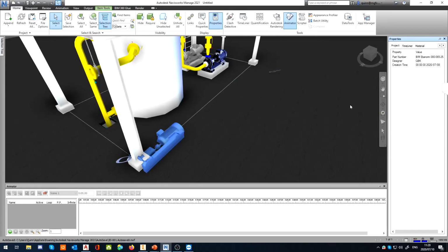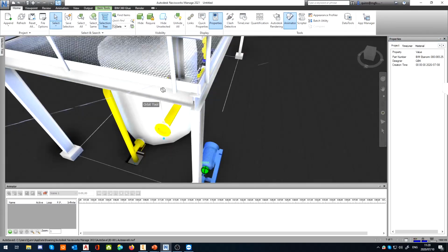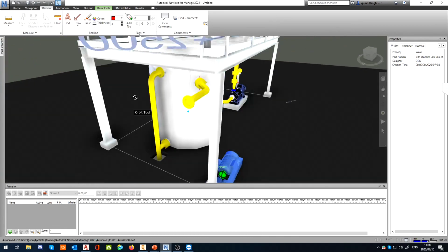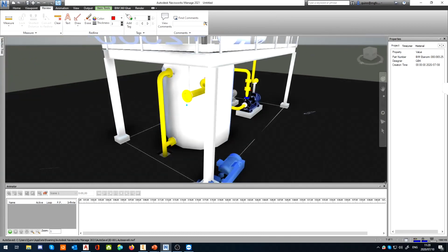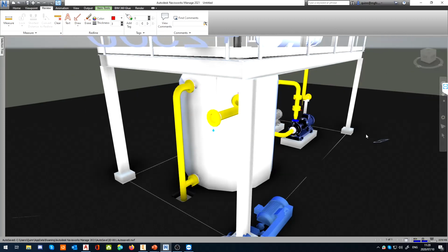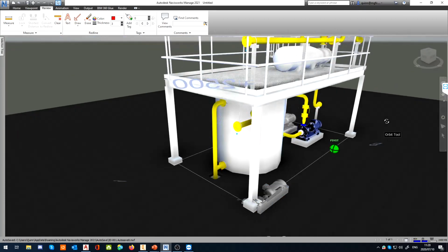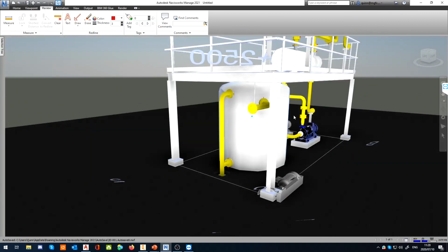By the way, this can also be done in Navisworks Freedom. They can do the markups, the viewpoint markups. So for review, they can do this in Navisworks Freedom, save it and send it back to you, so that you've also always got a copy of what was sent around. And then they've got the full 3D model with the markups and everything right there at their disposal.